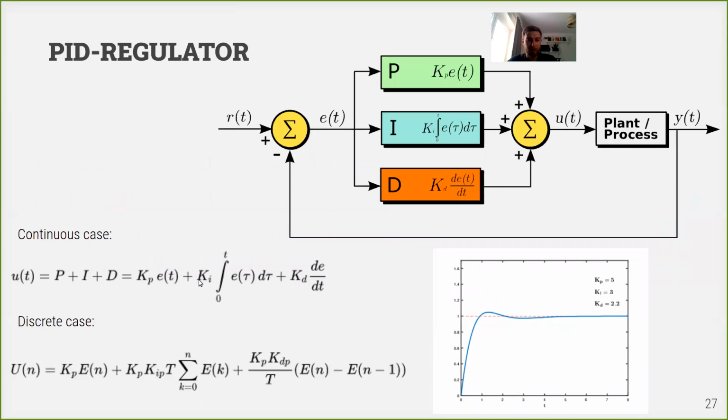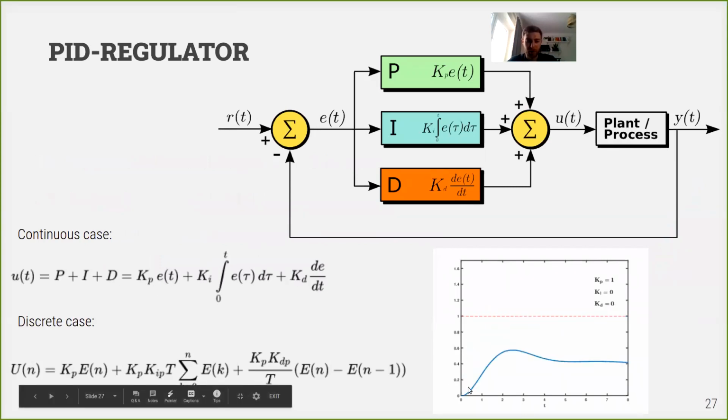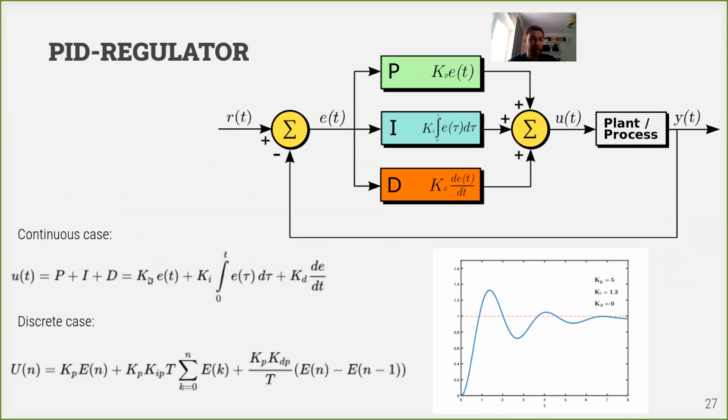All of the components are trying to solve some issues. So proportional is responsible for the majority of the signal. It just allows us to really quickly react to the error just by multiplying it by some gain. The integral part works to neglect the steady state error because it integrates error over time, and even if the error is small, we still will integrate it, and this time we will correct it with the integral coefficient.